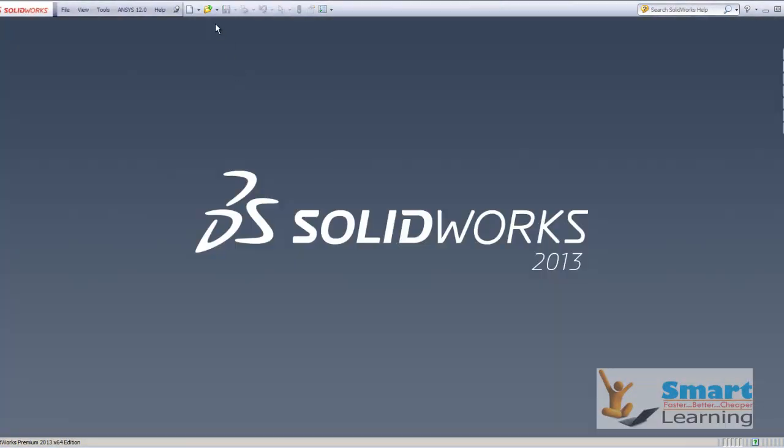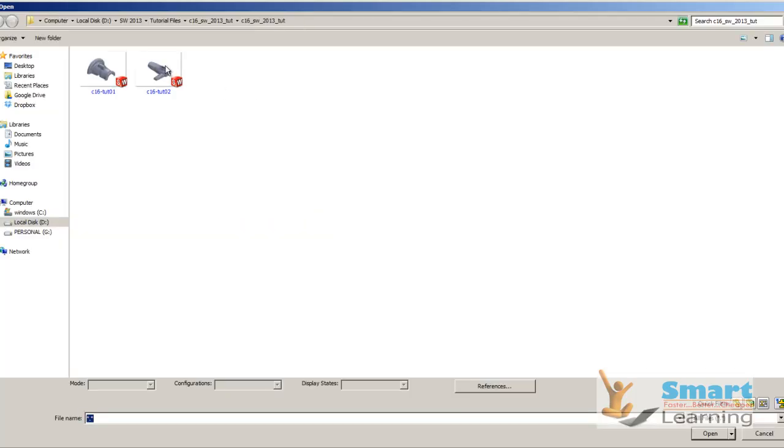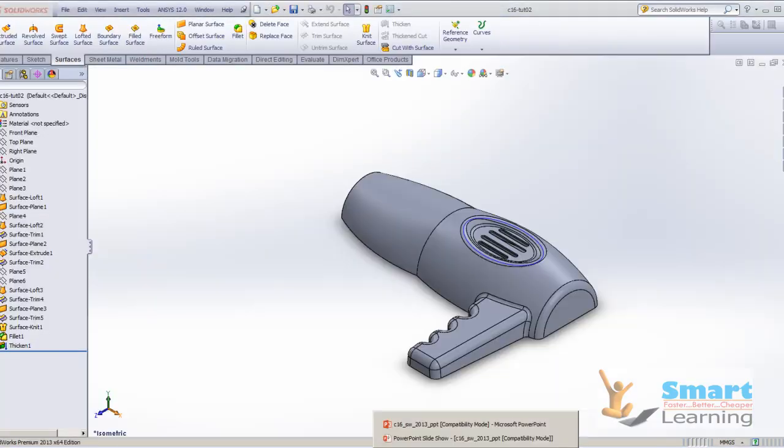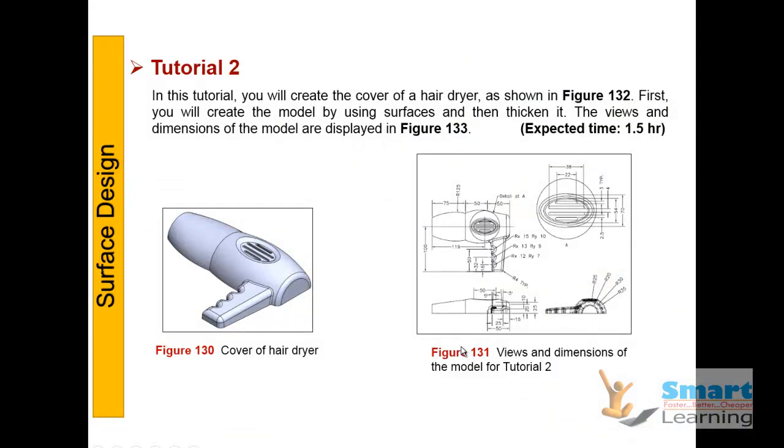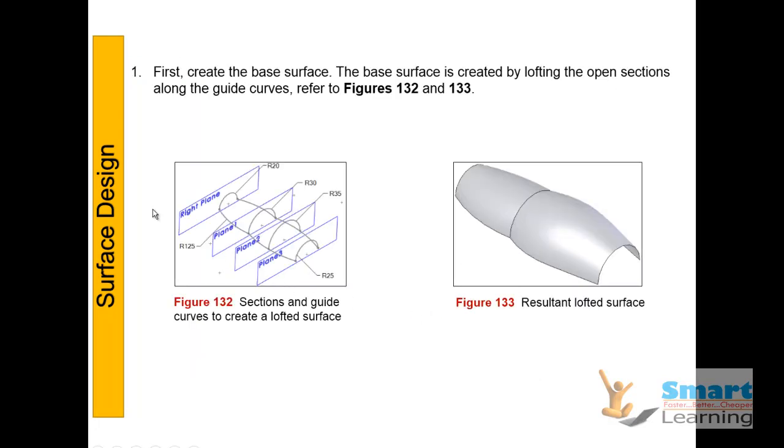Next we'll look at the other example which we are looking at. So for understanding this, have a look over this detailed dimension and complete this curvature. Here you have the Rx13 and Ry9 means elliptical. Here this is different, so this you have to track clearly. So we are starting with the 4 different planes where we'll be placing the curves and the corresponding guiding curves.